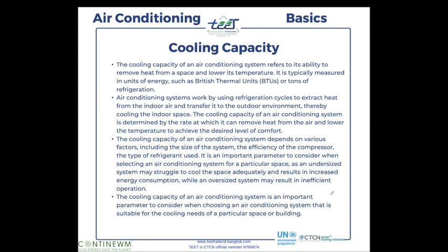On the other side, if it is just a little bit undersized, like we did with Anantara in Bophut, that's what we checked. They had a similar kind of room with a good cooling capacity for a 25 degrees Celsius set point. To make it simple, we saved something like 30% when we did the test at a 25 degrees Celsius set point.